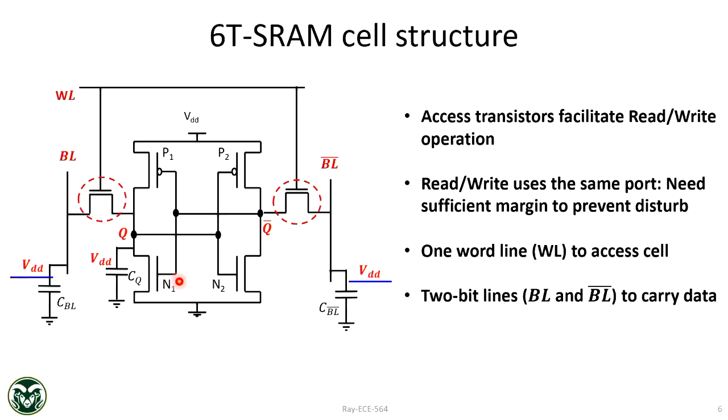So that's how you can think of it as a conceptual model, right? When Q equal to 1, that means this capacitor is at VDD, and Q equal to 0 means this capacitor is discharged. This is not a physical capacitor, this is a conceptual capacitor, right? In any CMOS circuit, every node has a capacitance corresponding to all the devices surrounding it: the source to drain, gate to source, right? Because this is connected to the source of this transistor, it is connected to this source, right?